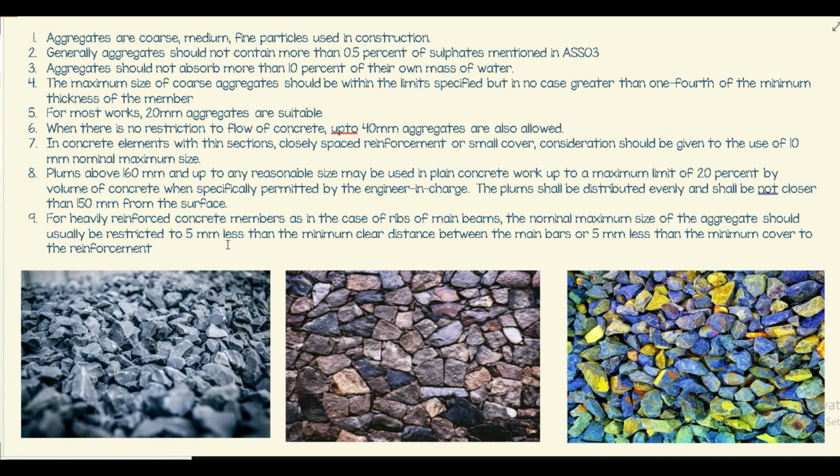I hope you guys are getting what I'm saying. The space between the rebars should not be left empty. We want the aggregates to reach those small spaces. So that's why they're restricting the size to 5 mm less than that distance.